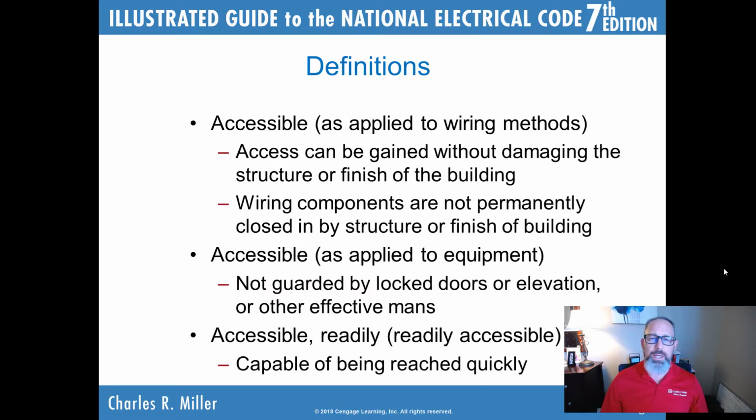You're installing an electrical junction box in a commercial building, let's say a school, and you want to put that box in, and you don't take into account the elevation drawings that show where the cabinets are going. And in fact, on that wall is going to be tall, 6-foot-high cabinets for storage in the classroom.